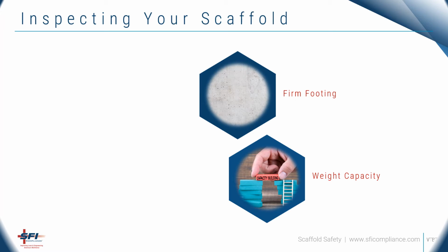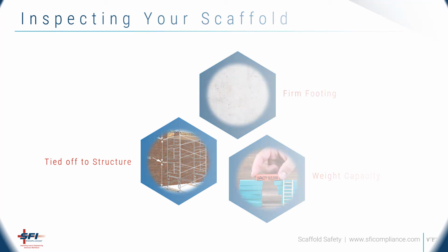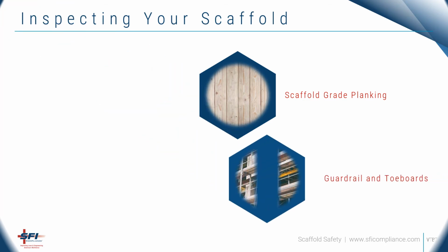The load includes not only the weight of the people on the scaffold, but also any supplies and equipment being used. When you reach 4 times the minimum base dimension, the scaffold must be tied off to a stable structure, such as a building wall. The planking used must be scaffold grade. The wood must be free of loose knots, splits, or other defects. Toe boards, at least 3.5 inches high, should be installed along the outer scaffold edge to prevent tools or materials from falling onto workers below.